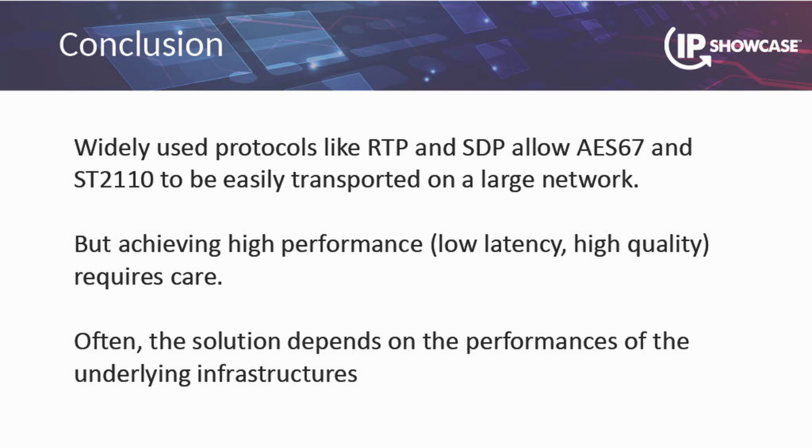So then that's it. Why do you use protocols like RTP and SDP? They are built into AES67, they are built into ST2110, and they are the key to transmit streams beyond the LAN. And this is exactly the fact that you go over the LAN, but you stay layer 3. And the fact that those protocols are purely layer 3 and not at all caring about layer 2 is the key in achieving high performance, but of course you need special care, especially in terms of synchronization, to reach those performances.